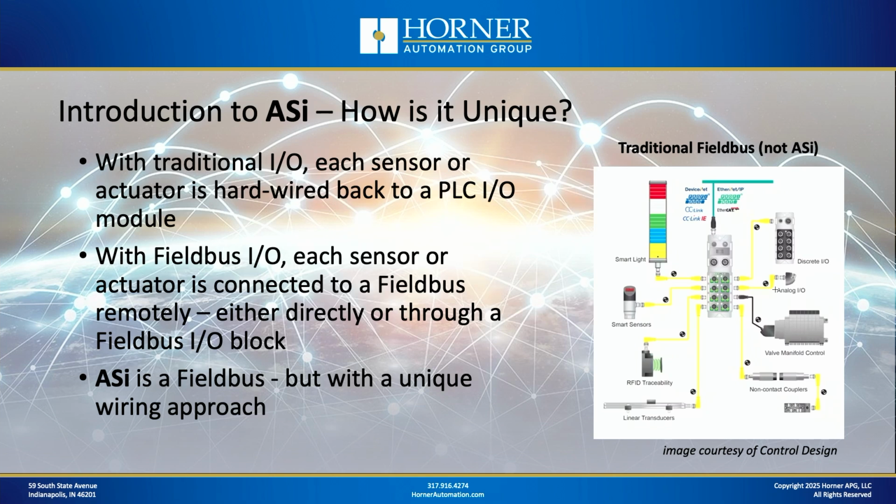Let's start talking about how I/O is traditionally wired to control systems, sensors and actuators, of course, and then we'll be able to demonstrate how ASi is different. Okay, so as most of us already know, with traditional I/O, each sensor or actuator is hardwired back to a PLC I/O module.